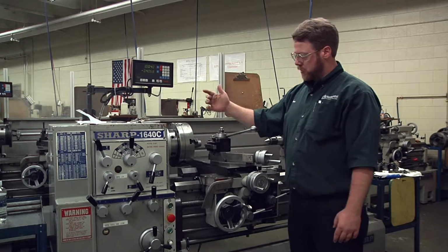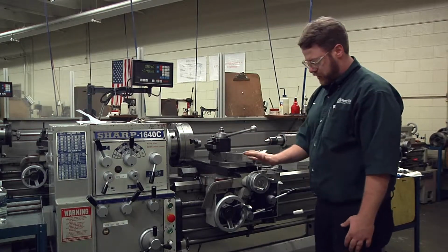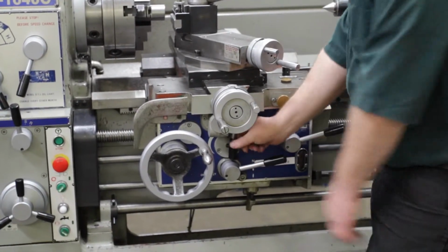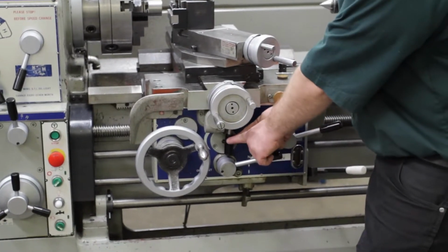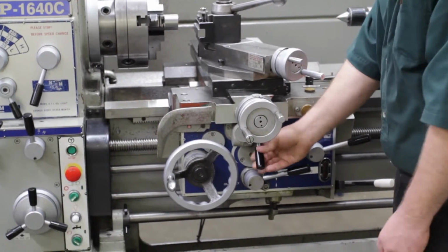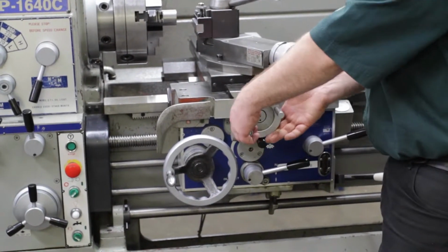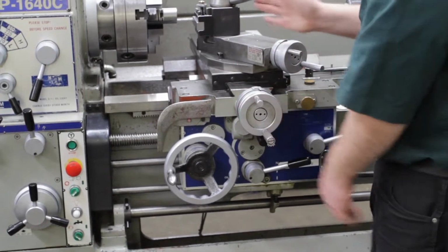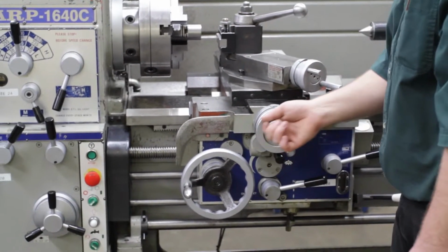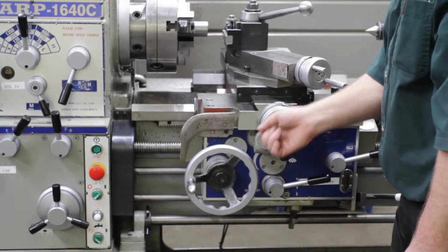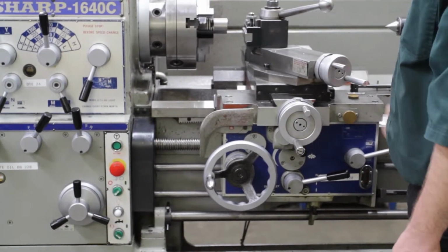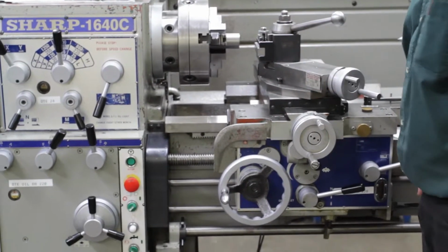So what I do there is I'm going to start up the machine. I'll have to set the carriage for facing. Remember, this handle changes the feed direction. If this handle is down, it'll control this handle. If this lever is up, it controls this handle. For a facing operation, you're simply cutting off the end of the shaft. So you're going to use the power feed in this direction. So the next step is starting up the machine at the proper RPM that we already have set.